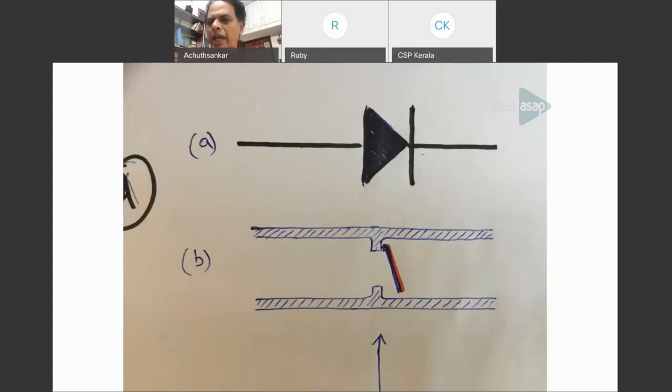So that has got a small height, as you can notice in the picture. So if you put a drop of water, that water cannot flow to the other side because it has to overcome that small obstacle. Also, the lid, when it is closed, if you put one drop of water, the lid will not open. So there is a minimum level of water pressure that is required for the water flow to start. This is very obvious common sense. Now this is called the cut-in pressure. When water will start flowing, that is called cut-in pressure.